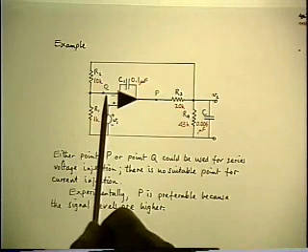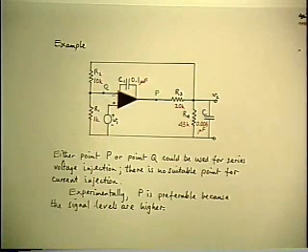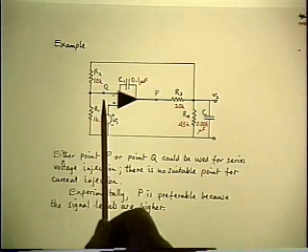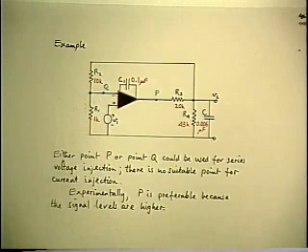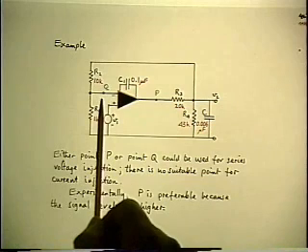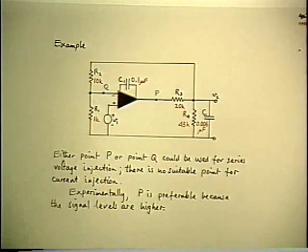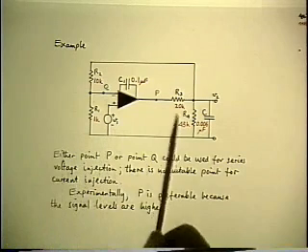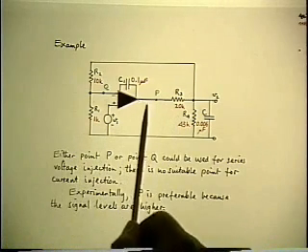So that would also be a good point to do series voltage injection, but only in principle, because the dynamic range of available signal there is tiny. And so you'd have a lot of trouble with measuring signals in the noise and hum pickup and a lot of other stuff. So the point of choice is clearly the output of the op amp, where you have the full dynamic range available.